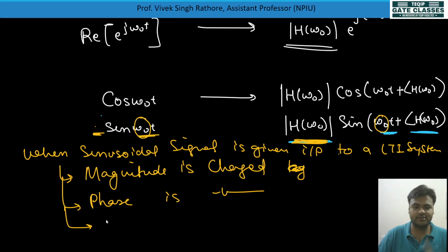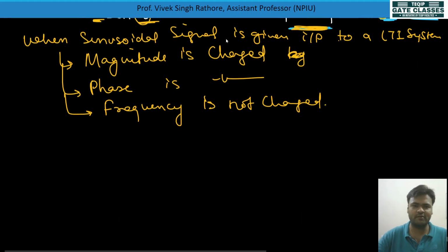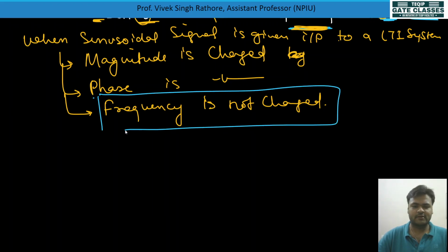No, sir, frequency is not changed. That is why this question has been asked in many questions: is the frequency changed? So frequency is not changed when a sinusoidal signal is given as input to an LTI system. This is a very important conclusion which we have got now, okay?